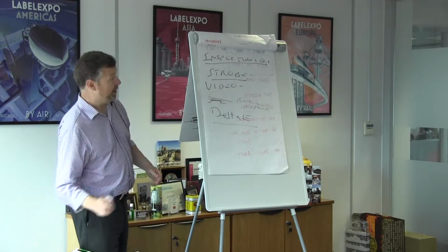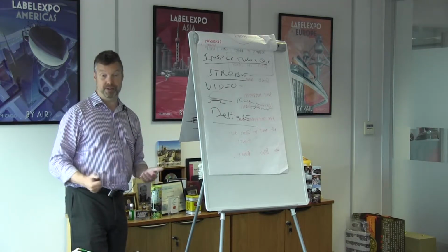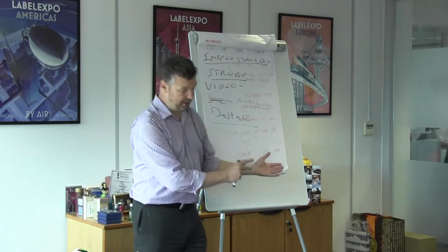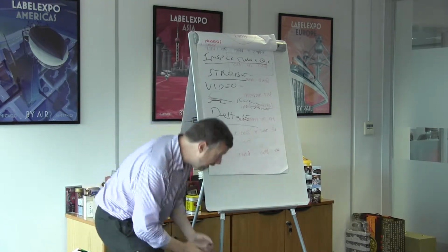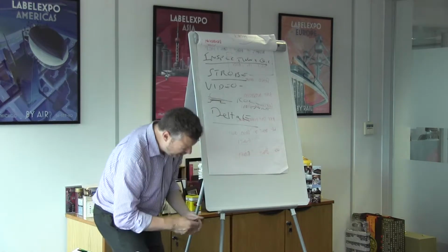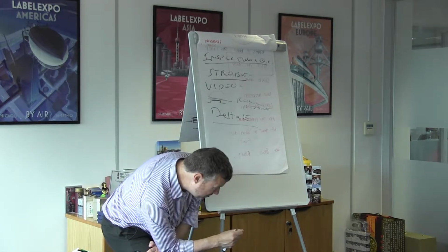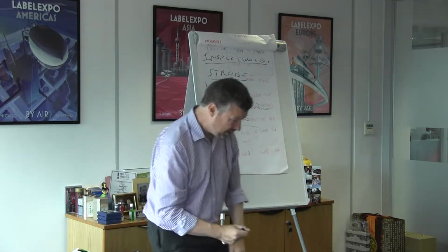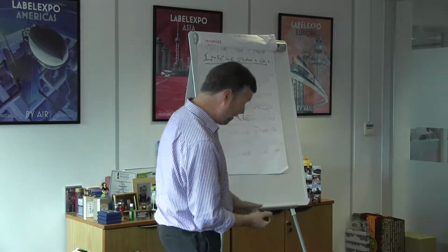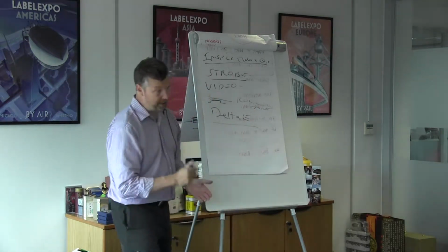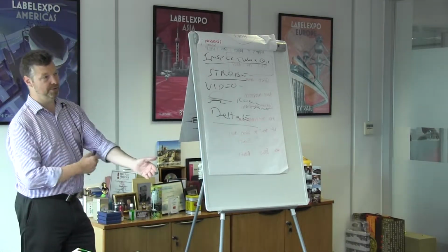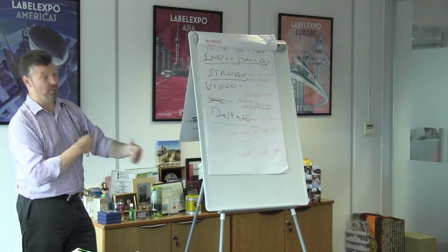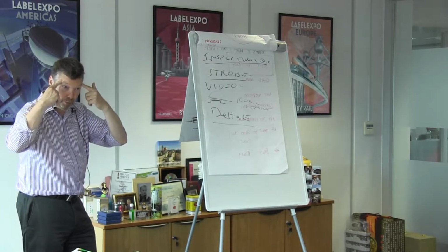And in the old days, which for most people is still the case, when you're making ready the press, the press is going really slowly, and what the operator is doing, they're going from print unit to print unit, and they're eyeballing it, and they've got a little pressure gauge, and they're just doing this and doing this, and at the end of the press, look at the camera, too much, come back and just back off the pressure a little bit. They're doing that to every single print unit. So one of the reasons that those flexo presses took so long to make ready was that all this is done by eyeballing.